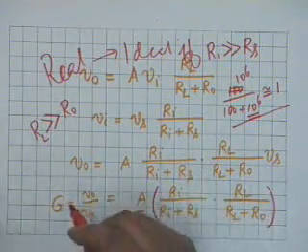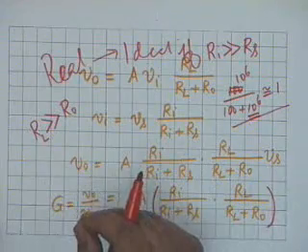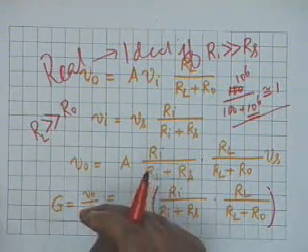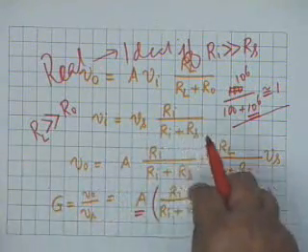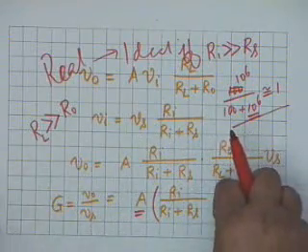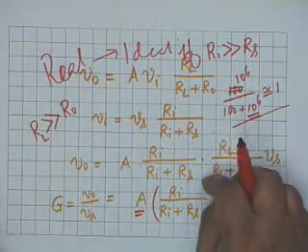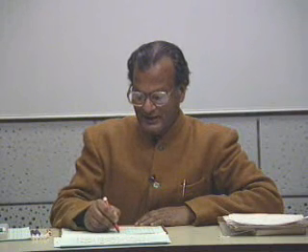So your amplifier design, your objective, should be to make as high an input resistance as possible and as low an output resistance as possible. This output resistance is obviously the Thevenin equivalent resistance. An amplifier which comes very nearly equal to an ideal amplifier is the so-called operational amplifier, which is available as an integrated circuit chip, an IC chip,